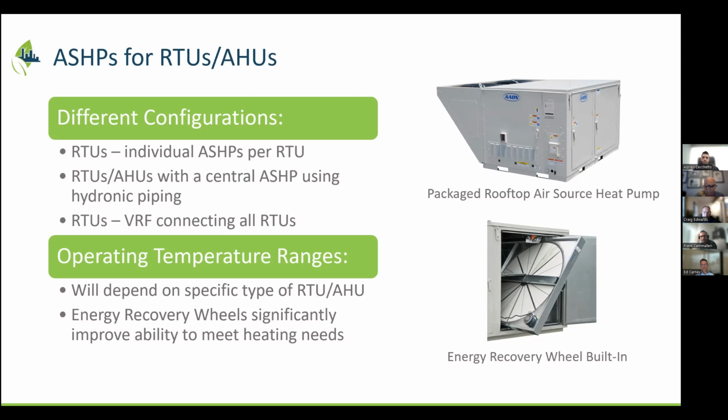Yeah, probably the easiest thing to implement is just a like-for-like replacement of a rooftop that's equipped with the air source heat pump functionality. So any of these units you see the picture of here could be ordered as an air source heat pump. You've got a certain power coming into the unit, and you can use that same power to make your unit into an air source heat pump. It's fairly quick and easy, and a very modest premium to do that. So that's the thing we're seeing the most of.